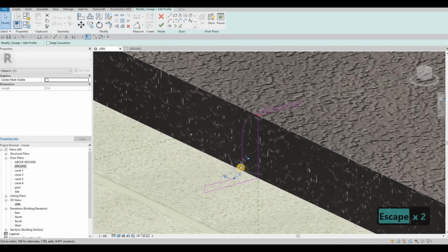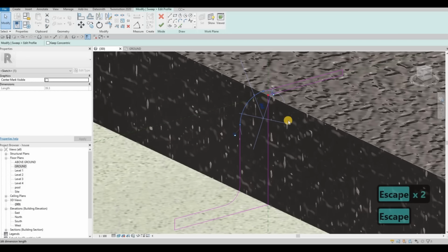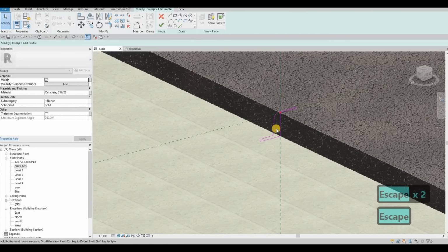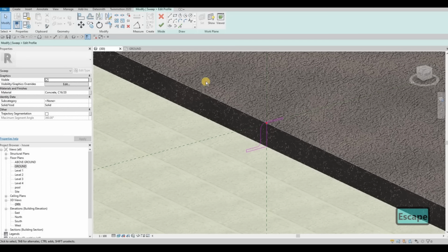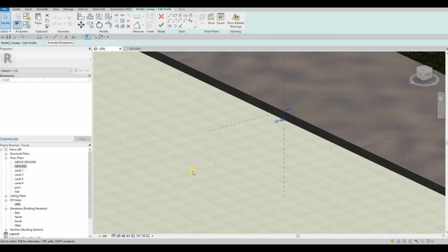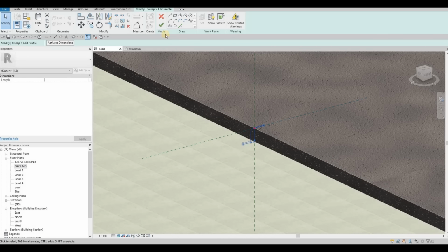Those simple arcs. So for this one, 15 for the radius, and then this one is 25 for the radius. It will really help us with realism. And then here, what you can do is Control C, or you can copy to clipboard. And this will help us do it on the others without us doing this again.